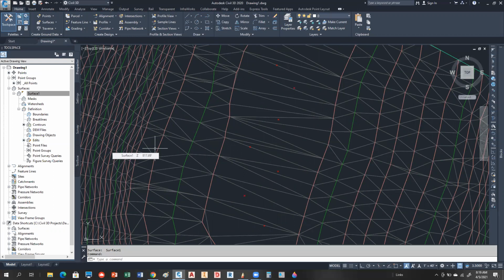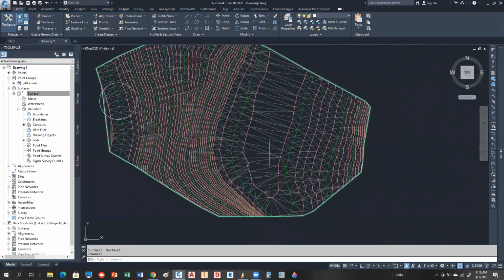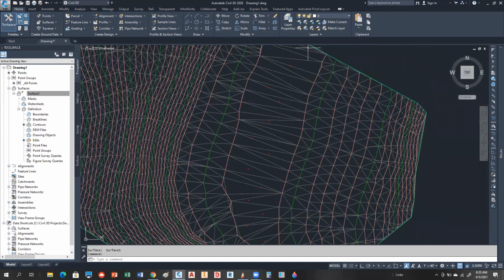That is basically a plateau or a mesa right now. It doesn't have any higher points to it because there's no information to make it higher. So essentially you have whatever that contour is to that contour, the same contour. This is a flat plane right now. Now, that could be reality, but it actually isn't because of the way it's working. So what we're going to do is add the point group in there, because those guys have elevations along that ridge that are going to edit that, okay?